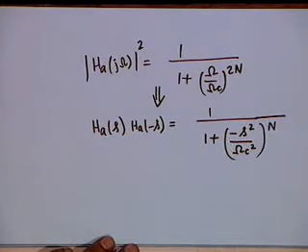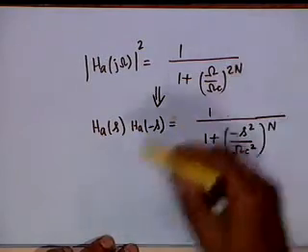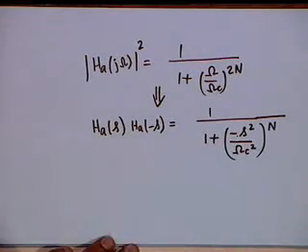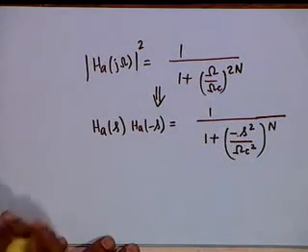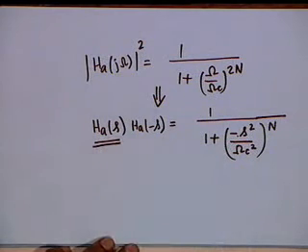All right. It is obvious that I can go from here to here by putting S equal to j omega, and the result is okay. From here to here is possible only if the function is analytic, that is, we are looking for an HA of S which has a finite number of singularities and the function is differentiable in the total S plane except at the singularities.